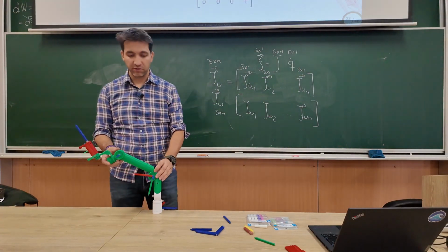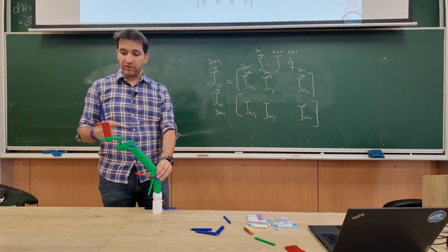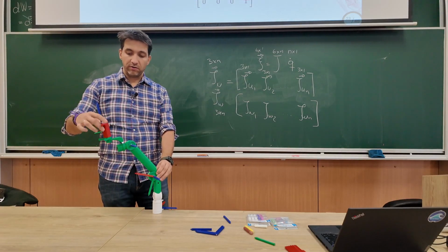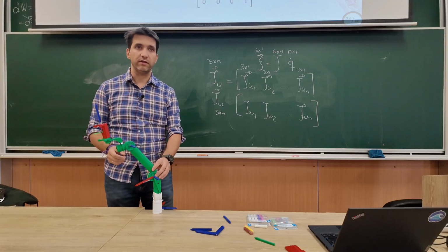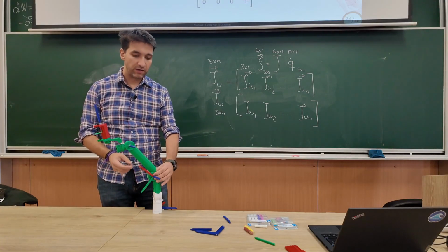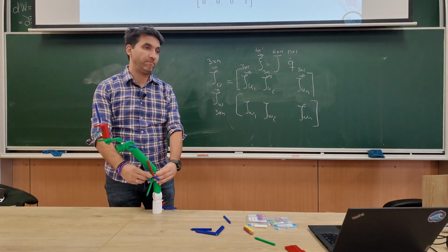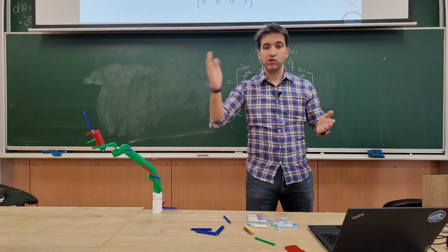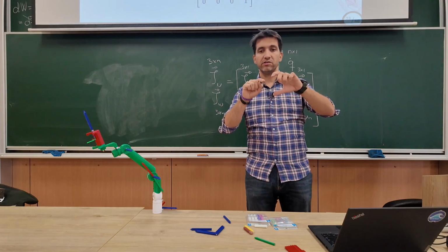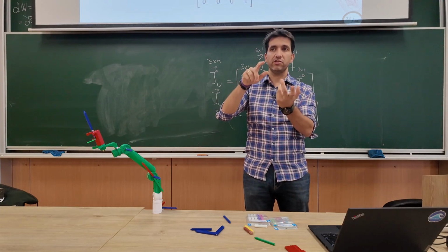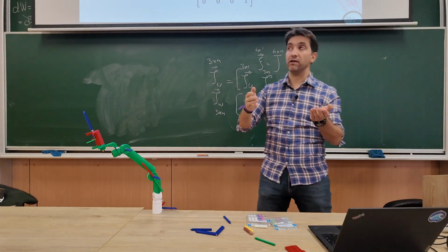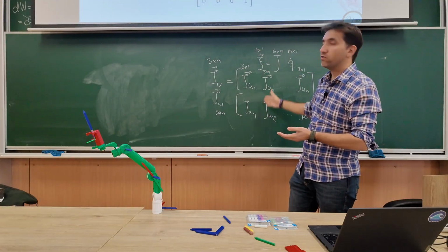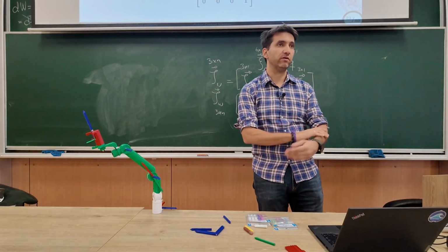I need to know just the forward kinematics for the end effector, but also for where each joint is. And then I can basically create a loop where I go for each joint, calculate where the origin of the joint is and what the orientation of the joint is, and calculate the corresponding column of the Jacobian for that joint.